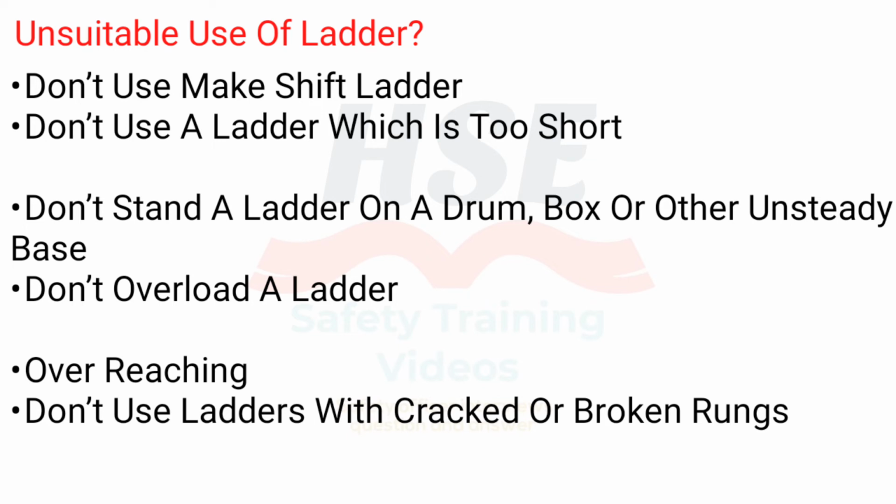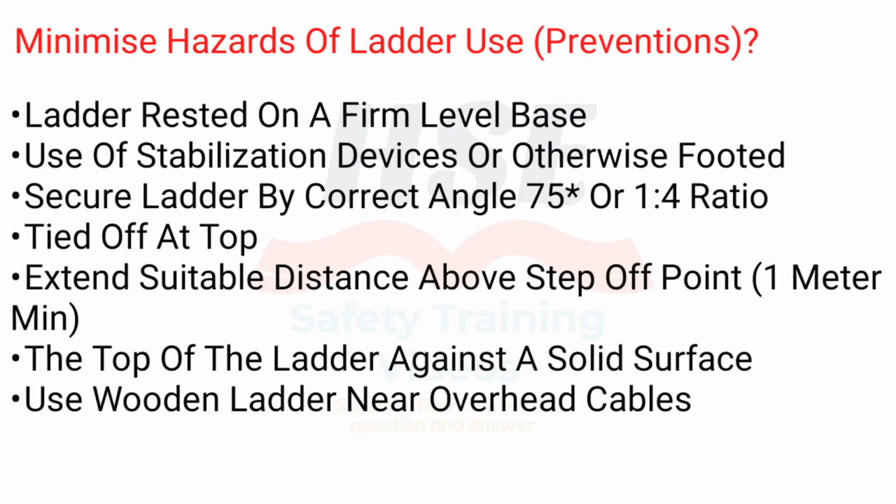Unsuitable use of ladders. Don't use a makeshift ladder. Don't use a ladder which is too short. Don't stand a ladder on a drum, box or other unsteady base. Don't overload a ladder. Don't overreach. Don't use ladders with cracked or broken rungs.